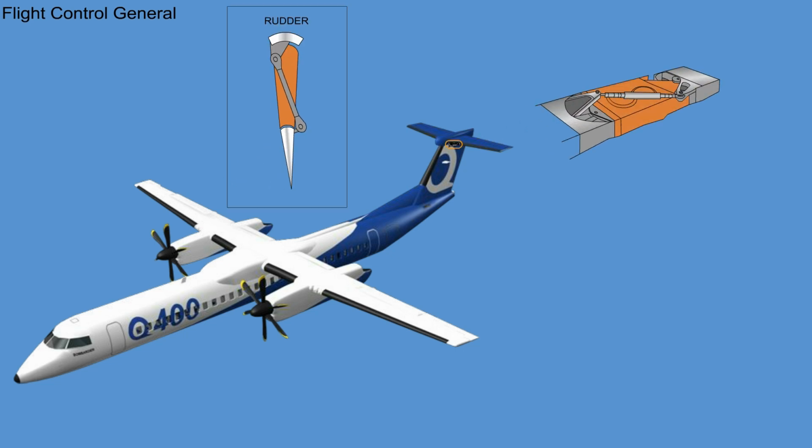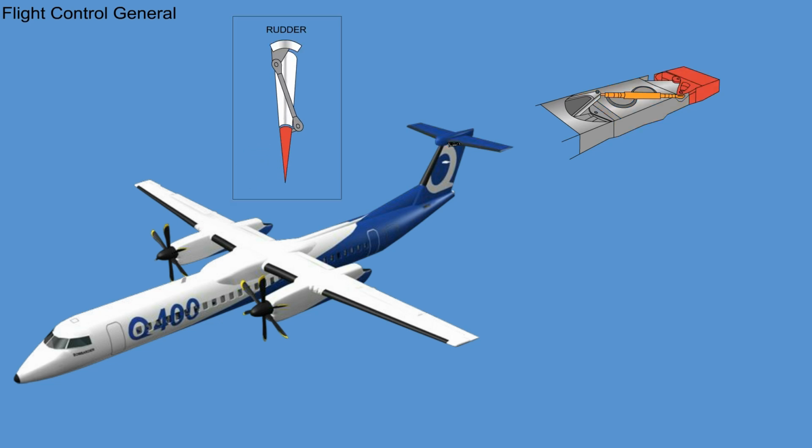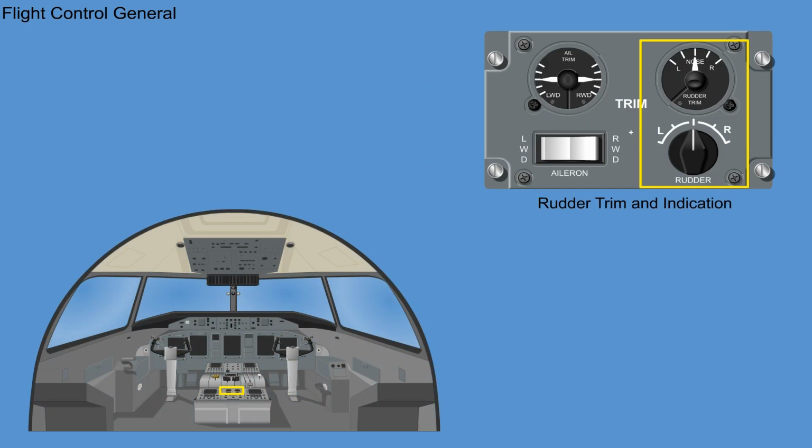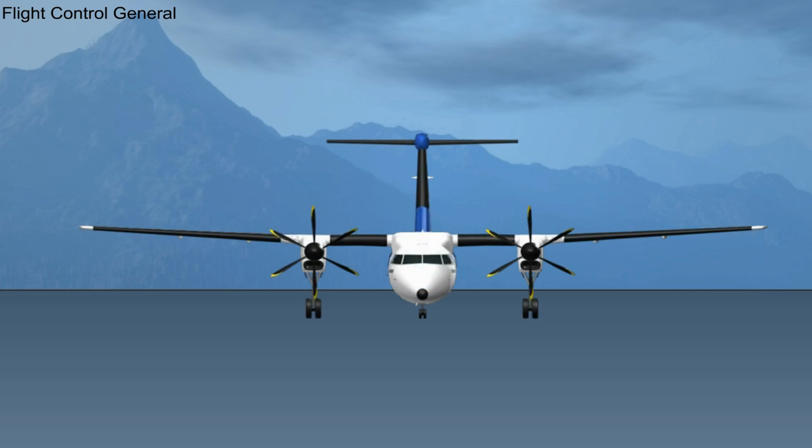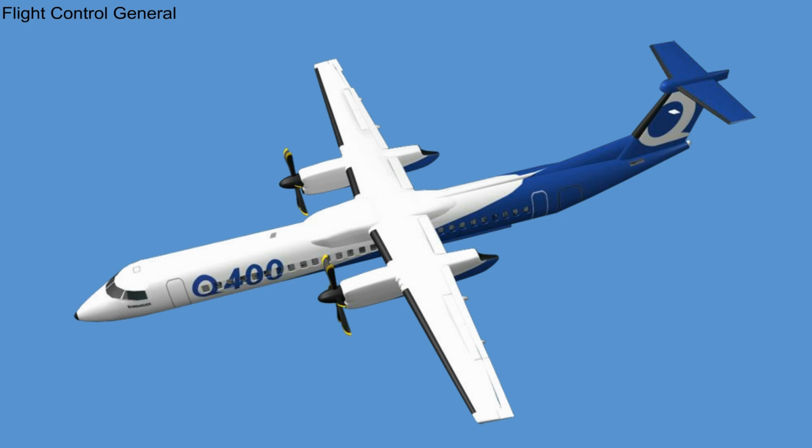The actuators move the fore rudder directly, while the trailing rudder is linked geometrically to double the movement of the fore rudder. Rudder trim is provided by an electrical actuator. If the system is without pressure, a rudder hydraulic damper maintains rudder position against wind gusts.